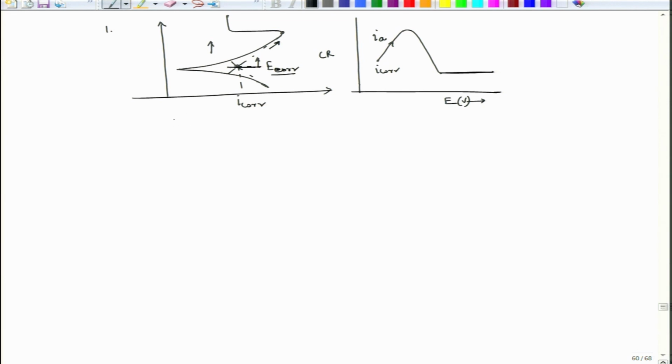The other nature is, let us say, the change in concentration. So, the corrosion rate, CR, with concentration. For example, in the very experiment that Faraday did, if we put an iron block in dilute HNO3, the corrosion rate would be high. As we increase the concentration, we keep having an increase in corrosion rate, but at some critical level the corrosion rate suddenly drops.